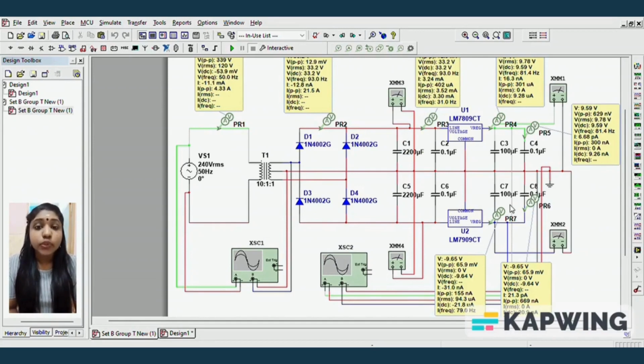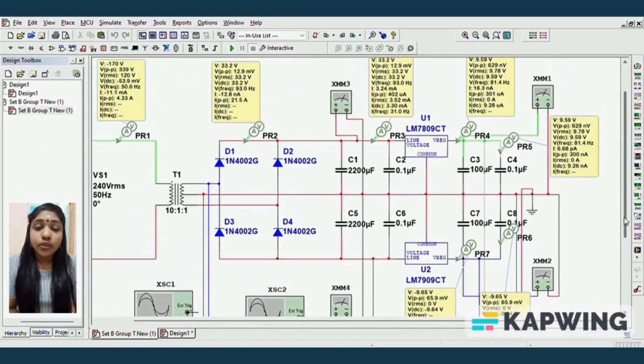Next, the first two multimeters are connected to measure both the positive and negative voltage values of the final output. The positive probe of multimeter 1 and multimeter 2 is connected near the C3 and C7 respectively. Then, the negative probe of both multimeters is connected to the middle wire as it is the negative side.